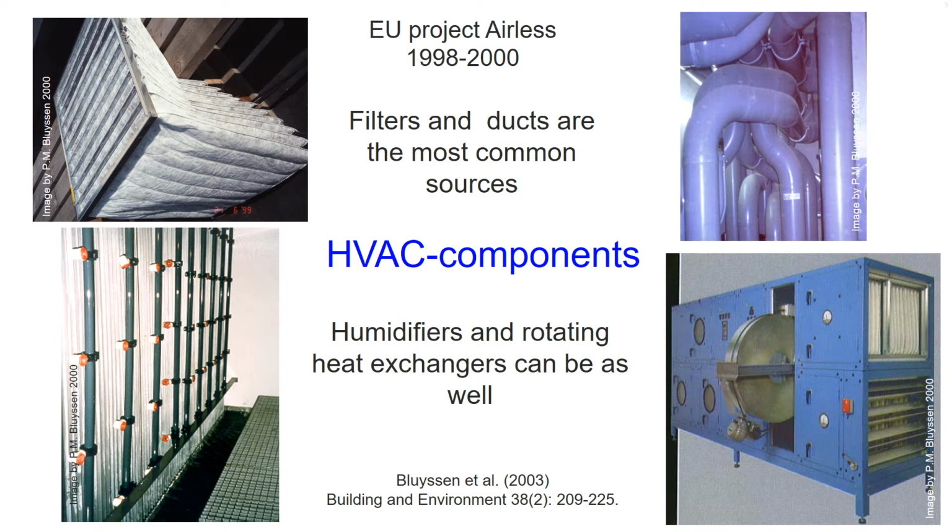In a European project named Airless, partly funded by the European Union, which took place in the period between 1998 and 2000, the air pollutant effect of several components of HVAC systems were tested, both with trained panels that evaluated perceived air quality and with common measurement equipment. The outcome showed that especially the filters and the ducts, but also humidifiers and rotating heat exchangers, had the potential to pollute the air, if not designed and maintained properly.